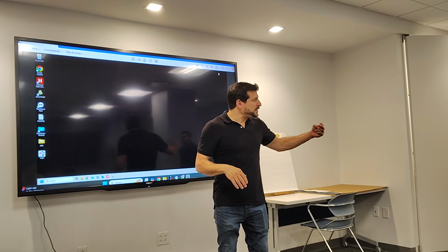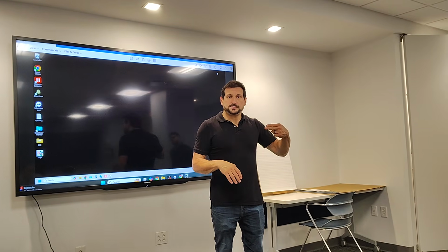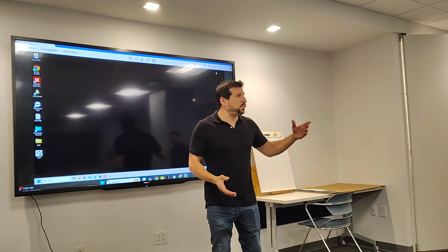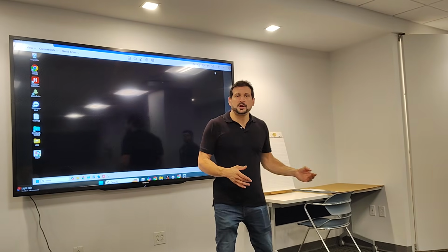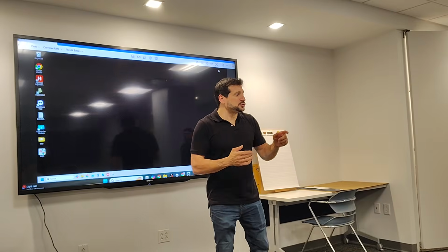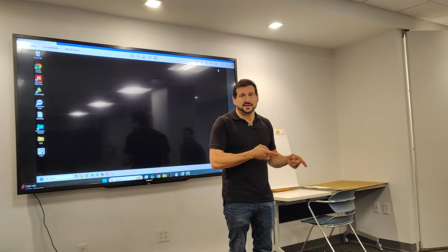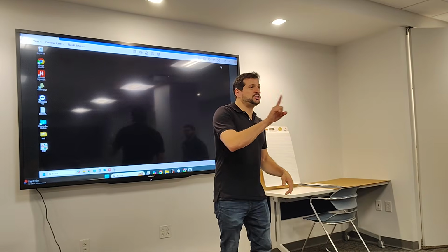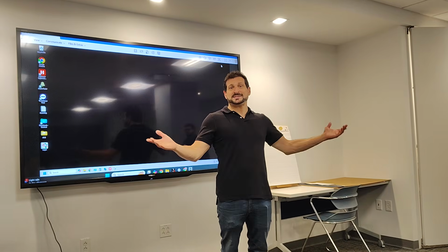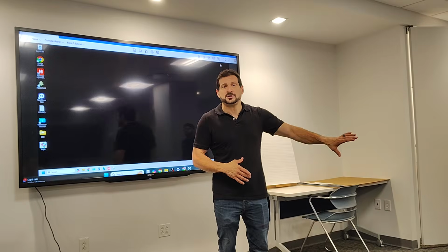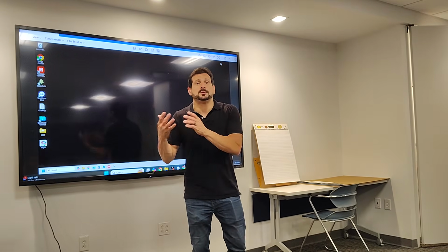We don't ever change the inputs. That's our eyes and ears to the world, right? So what's the temperature of the room? Well, we don't want to lie to the BMS and tell it the wrong temperature. If you're looking at a graphic and you see, oh, my space temperature is 78 degrees, they're hot. I'm going to change my space temperature to 68 degrees, now they're not hot. All you've done is told the BMS the wrong information, and it's actually going to make your problem worse.